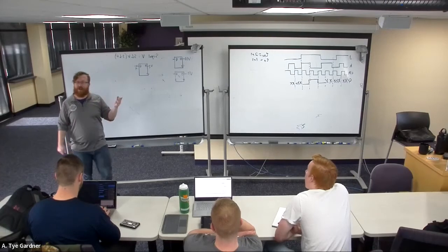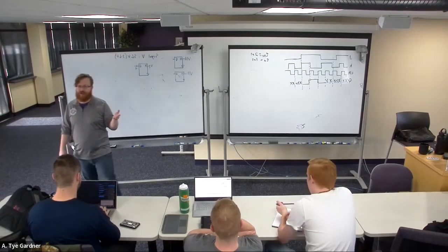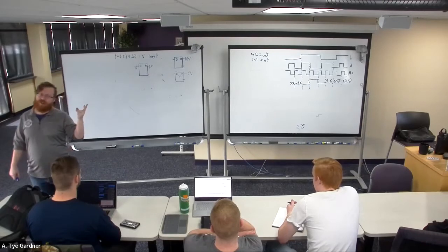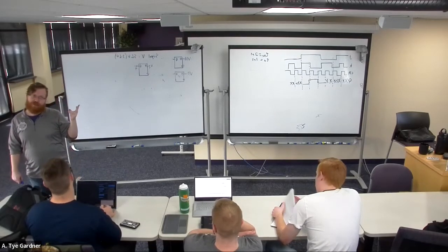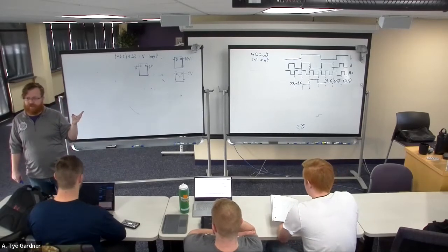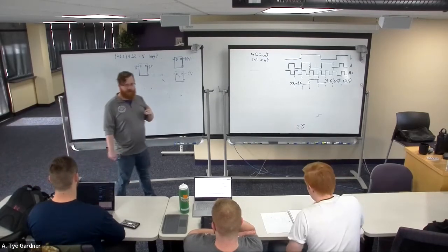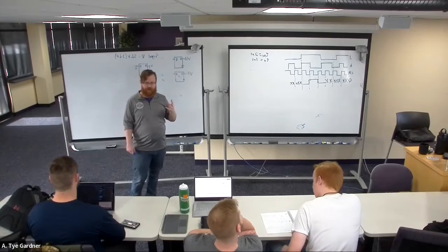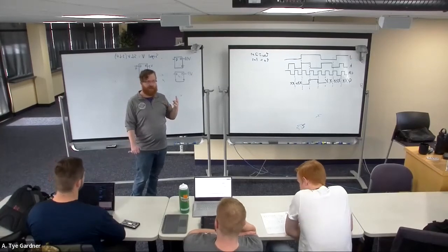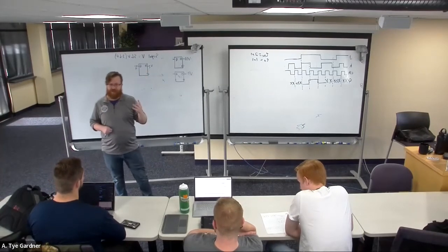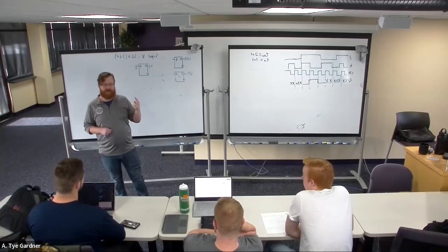And you'd have, right, I don't expect you to have that memorized. You go back and look at your notes and be like, okay, well, an SR latch takes 2 NOR gates. Turning that into a D latch takes 2 more NOR gates. So we're up to 4. And then we need 2 of those D latches to make a D flip-flop.